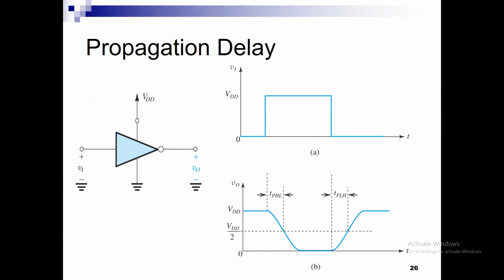Okay, so just like there is dynamic power, where we need to charge and discharge a capacitor, anytime I have a C, I have an effective RC time constant, and therefore I have a delay. Now, typically for our purposes, we are going to assume that the input is switching instantaneously.